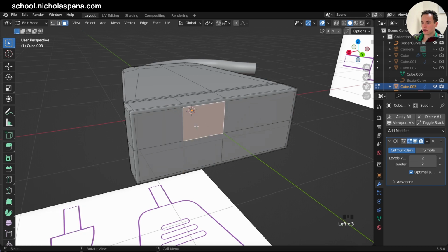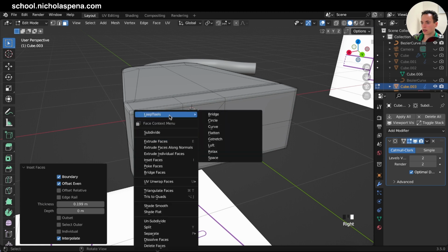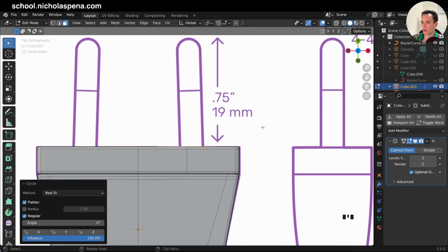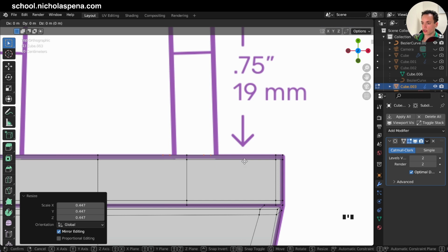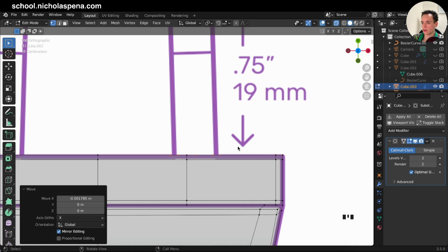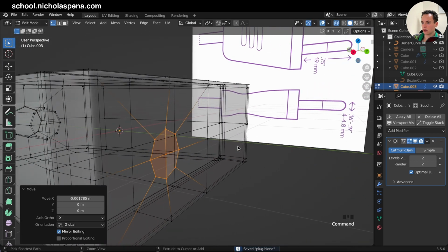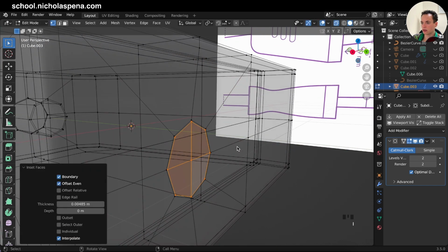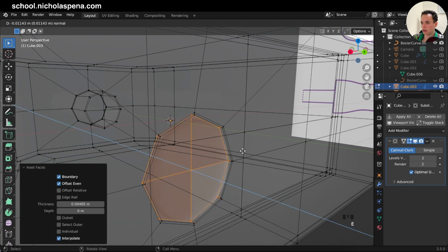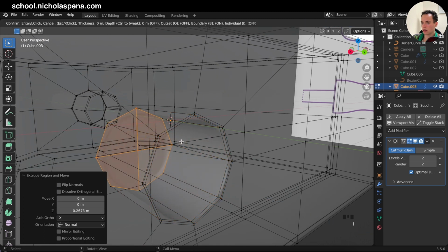So get the faces, shift click, do I inset, right click, loop tool, circles, go on top, go on X-ray and vertex select, S, you can see the point, G, X, to move like this, S, like this. Now we have this, we can I inset again a little bit, E, E again, I, like this,